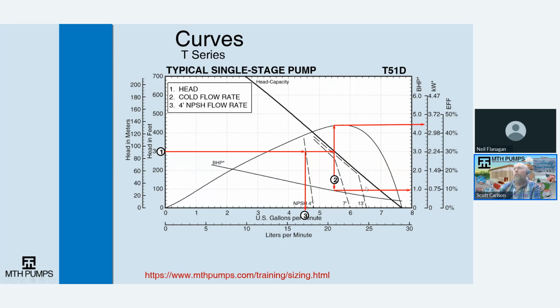With a regenerative turbine pump, as the NPSH becomes less available, because all of the work of the water is being done on the outside of the impeller, any of the bubbles that form from water boiling would just go out with the rest of the pump, and it would displace a little bit, but it would not completely stop operation of the pump. So here, if there was only 13 feet of NPSH, this is where you'd start seeing it degrade a little bit.